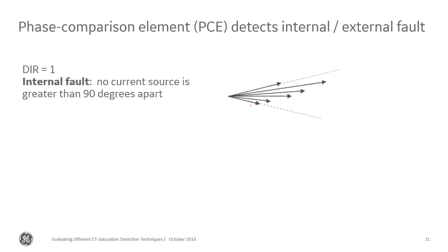All of my fault currents will be in the same direction. So they'll be either 0 if there's no source for them, or they will be flowing into the zone of protection, which will look like 1 per unit at 0 degrees and 1 per unit at 0 degrees. And so when I see that, the relay can set a directional flag. It'll set that directional flag of 1.